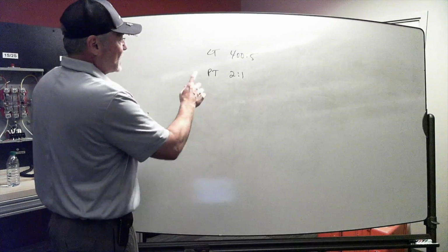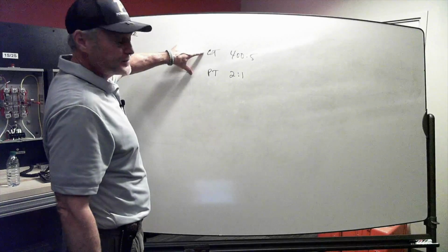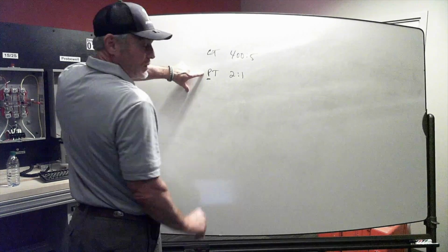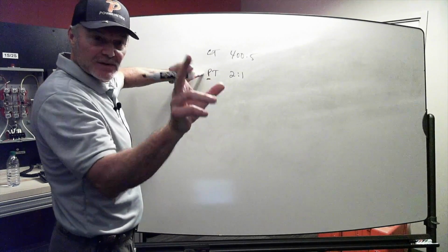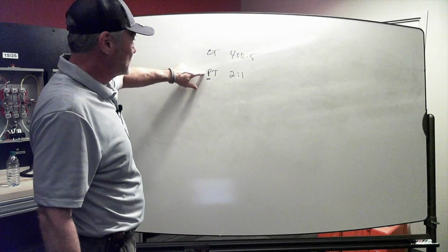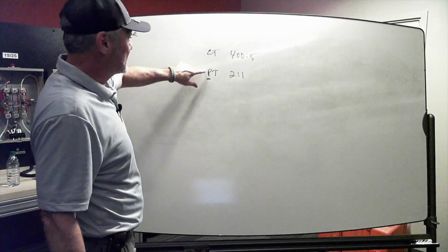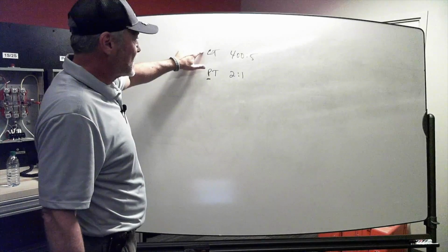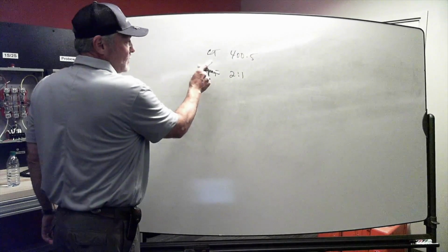So we've got our step-down transformers. We've got a CT that's stepping down my current. I got a PT that's stepping down, instead of voltage, we use potential, right? Just like when you're talking about potential on a battery. Some people use VT for voltage transformer. You see on some of these packs out there now, VT packs. But right now, we always go CT and PT. So this is taking my current down, and this is taking my voltage down.